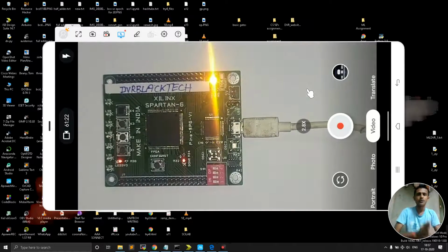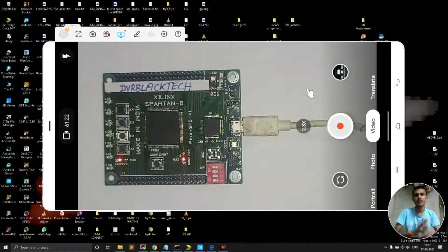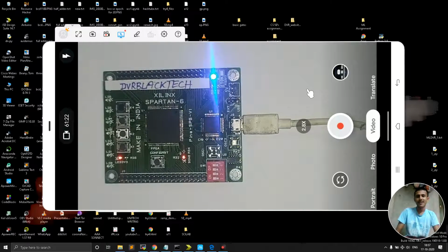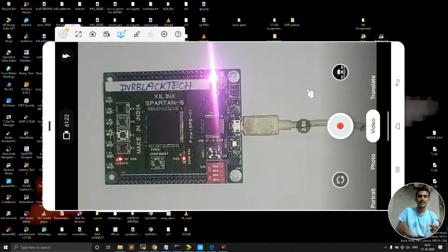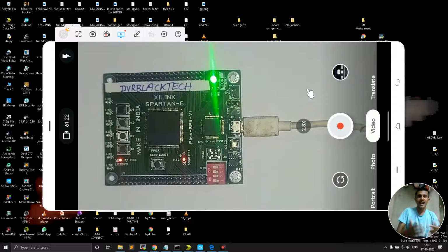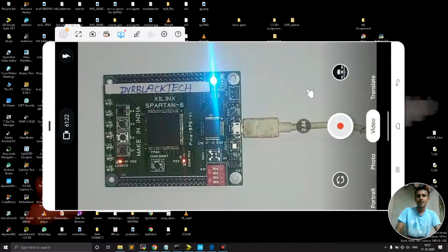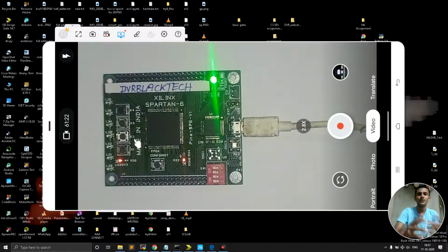Now we are going to follow the same steps, but now we are going to write the code for the half adder. It is okay, just a single bit half adder. That means A, B, two inputs, and sum and the carry. Sum is going to be A XOR B and carry is going to be A AND B. That we already know. Now we are just going to do the same thing and implement that on this board.